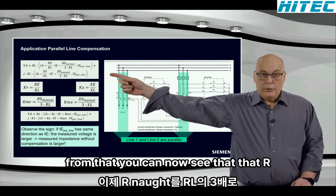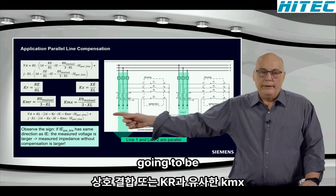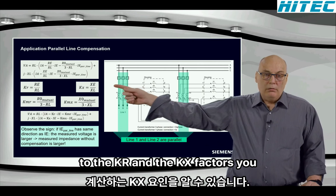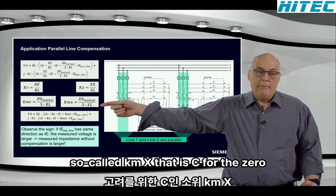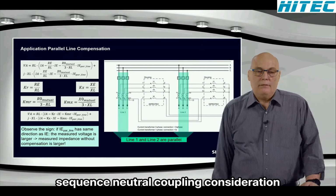From that, you can now see that R0 divided by 3 times RL is going to be our mutual coupling or KMX factors. Similar to the KR and the KX factors, if you have a parallel line you calculate a so-called KMX. That is for the zero sequence mutual coupling consideration.